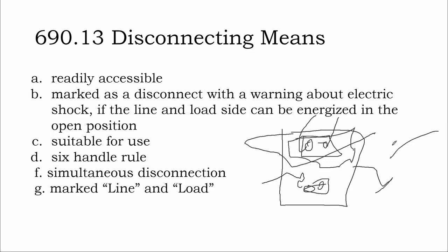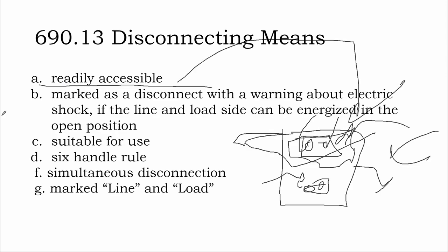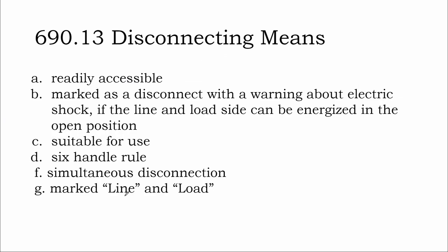Someone else could misinterpret this switch being down as off and this lid being open to reach in and touch those terminals because they want to do some amateur wiring work and electrocute themselves. And that's why these readily accessible disconnect switches need to be locked so that only people who should be in them can get in them.